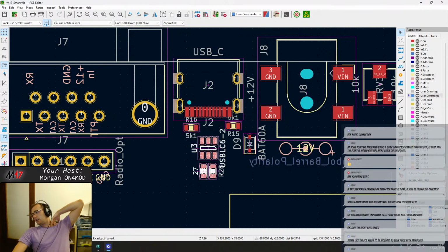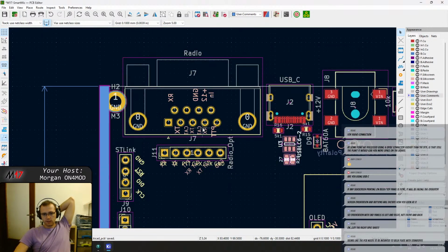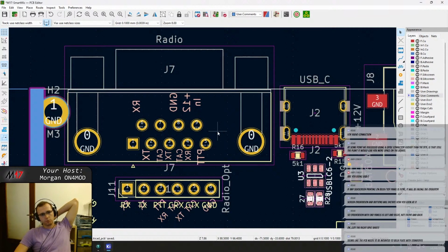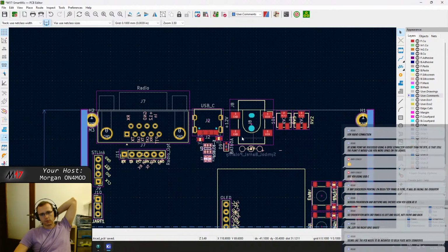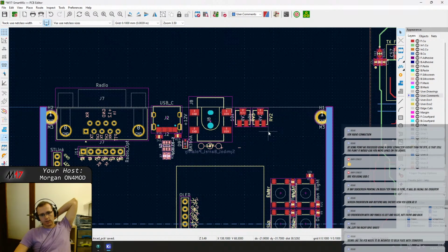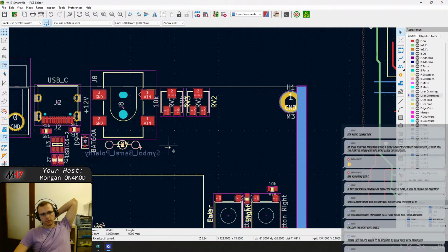Yeah, using IPHC would give us more space on the board. We even discussed using Minidin, because Minidin 6-pin is what is used by some big manufacturers like Yaesu, ICOM. But in the end, we decided to keep the connector that we used previously because we didn't want people to have to remake a cable. So yeah, we just decided this.